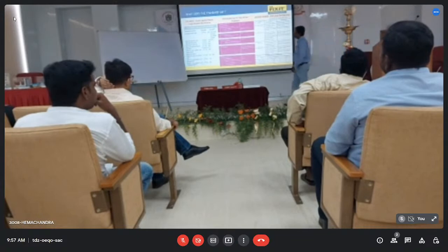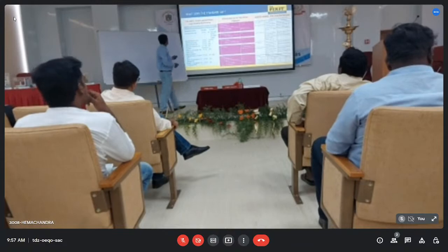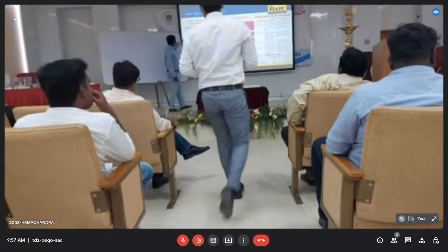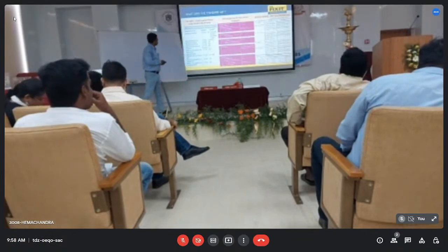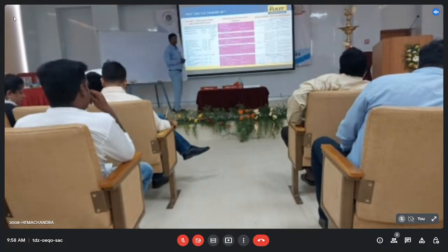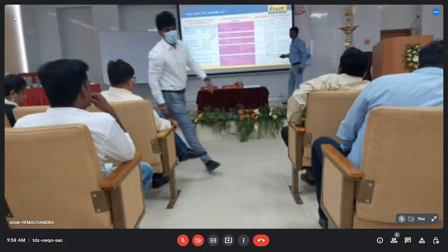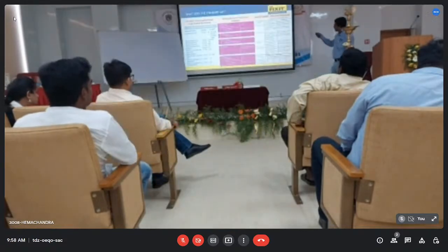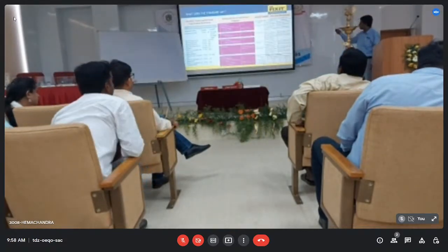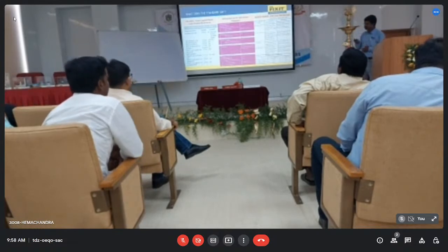First is EN 1489. Fundamental characteristics: initial adhesion tensile strength 0.5 Newton per mm². Okay, this is very important: tensile strength of the product and good bonding. Just sharing. So these are the details, the main technical parameters we should follow.